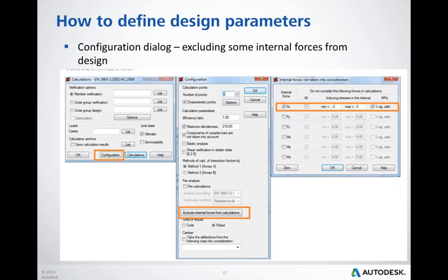Mind that when you want to disregard both positive and negative forces, for example small tension and small compression, you need to enter both positive and negative values. It is recommended to use the relative limits, being the percentage of the admissible stress, rather than set absolute values, as such a setting can be used for all sections regardless of their sizes.